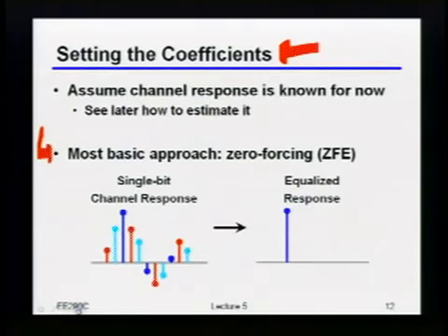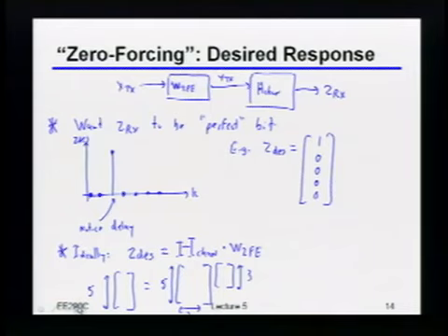Actually, I have a question about the number of taps. The more taps you have, it's kind of like you're going to translate into latency, right? Is there any case you actually care about this latency? That's a great question. Indeed, there are many cases where you really do care about the latency. Specifically, if you're talking about something like a microprocessor talking to another processor, or a processor talking to a graphics card, you do care a lot about the latency. So if you end up inserting a lot of latency because of some equalizer you're using, that could actually be a big deal.